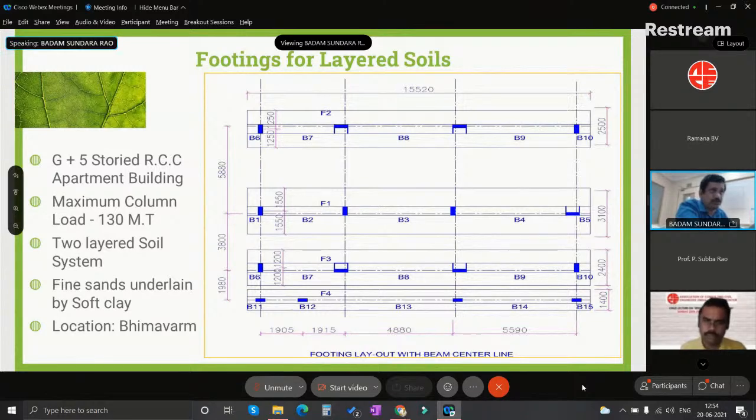This is an actual strip footing. For the strip footing, we have designed the foundation system accordingly by restricting the bulb of pressure. That was the concept adopted here. Therefore, we have to think about the minimization of the width of the foundation. Thereby, the total settlement was minimized.